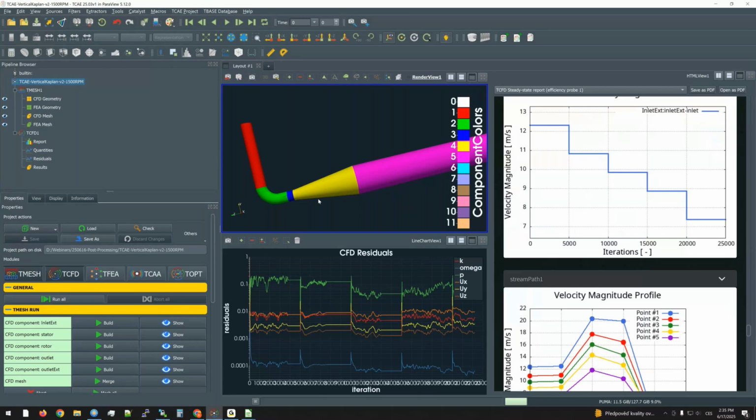And then if you would like to study the local properties of the flow, or evaluate visualizations, and for example compare some specific part of your simulated domain or of your machine with a previously simulated case, for example if you are optimizing the shape of the blades or any part of your domain, then you can visually compare the differences of pressure distribution, or for example the flow separations at the given parts.